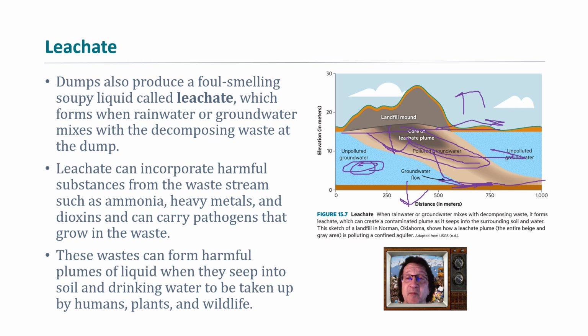So you have to pay attention to the flow of the plume too. If you're living in a house right here near a landfill, which is very typical in many areas, and if you're getting groundwater through a well, you're in real trouble. So we have to pay attention to this when we look at landfill design. And this is why just dumping garbage on the soil is a bad idea without treating the soil in some way or producing a formal pit to put it in.